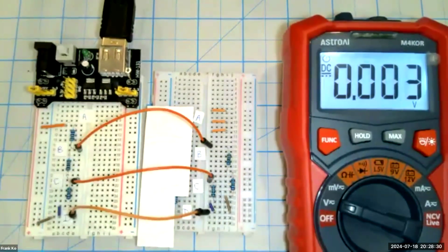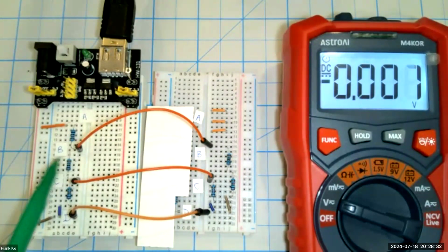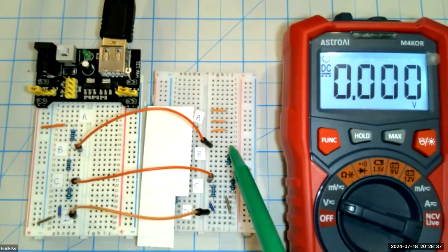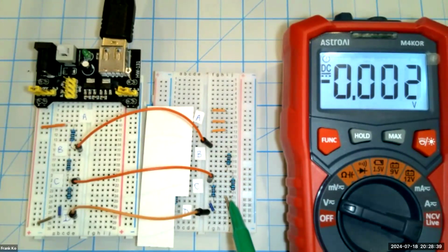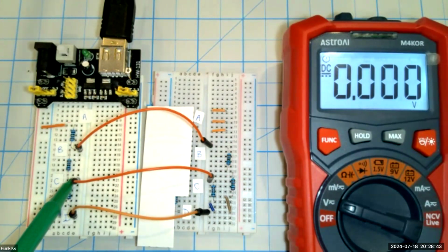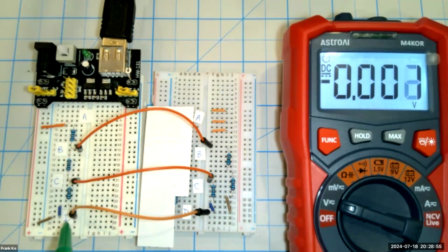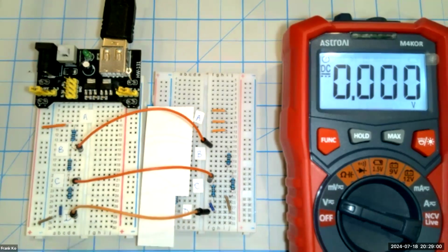Looking at this very carefully. Point B is now attached to point B, the top of your R5 resistor, 4K ohms to ground. Point C originally was 2 volts, and 2 volts to point C over here to the top of the R4 resistor, and then the bottom of these 2 loads are attached via this jumper to the bottom of the voltage divider, completing our circuit.